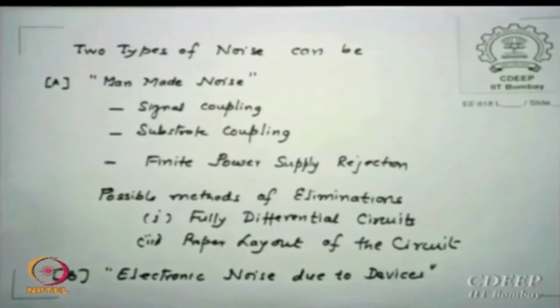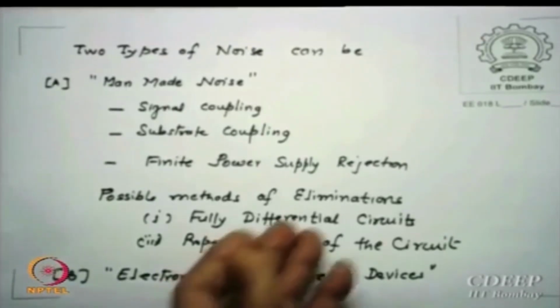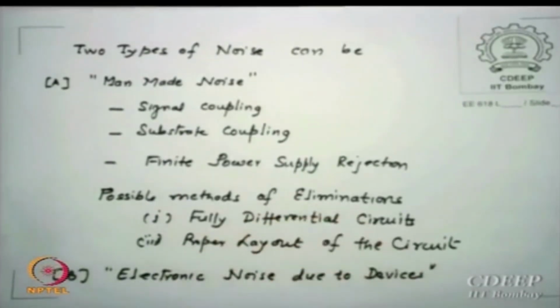So we will come back to layout and discuss why common centroids. At that time I would say this layout, taken with care, helps you reduce noise in particular, and this is very important in real implementation of layouts on chips. So this is relevant. Of course, if you do this properly, you can contain noise to a great extent.